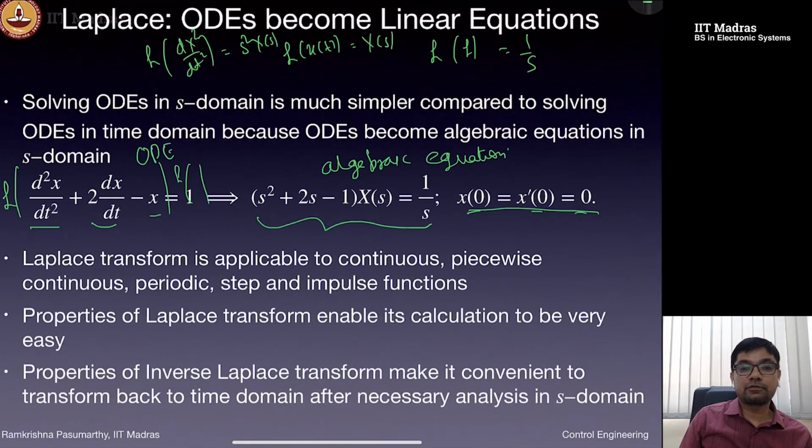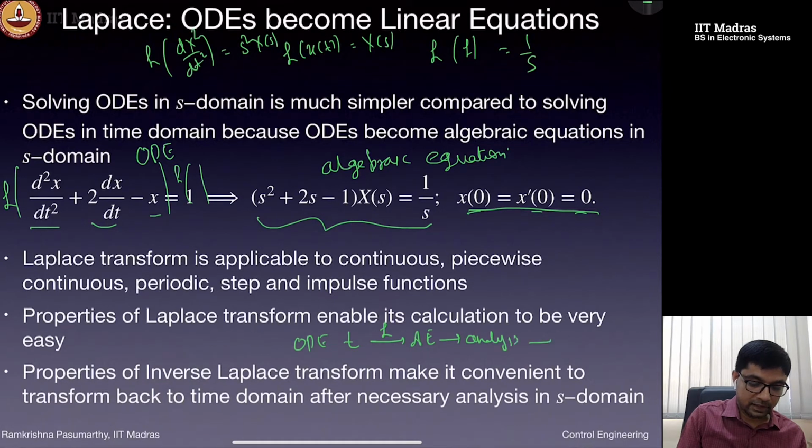And this Laplace transform is actually applicable to several kinds of signals. Signals could be continuous, piecewise continuous, periodic, step, impulse functions, and so on. And the properties of the Laplace transform that we saw, from linearity, differentiation, integration, to time scaling, make the computations very easy. And not just that, inverse Laplace transforms also retain all of those properties. So the recipe again would be to start from the time domain, go to the Laplace domain, convert the ODE from the time domain to an algebraic equation, do the analysis, and apply the inverse Laplace to come back to the time domain.